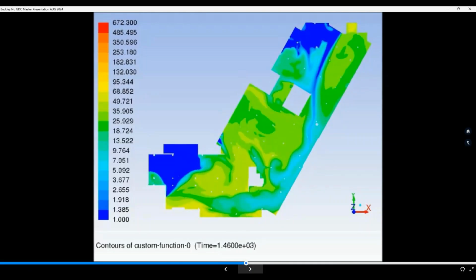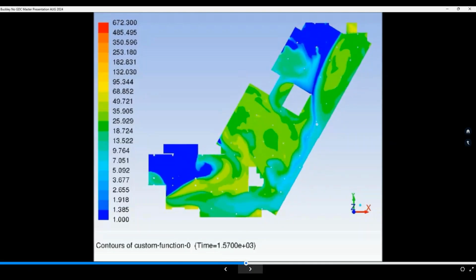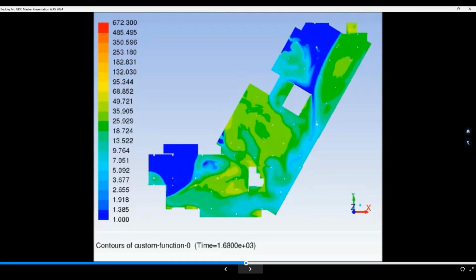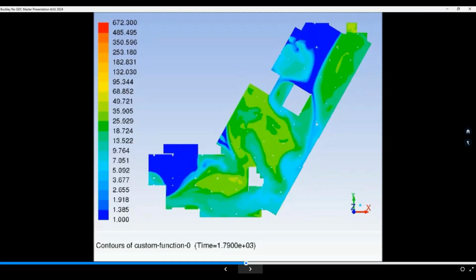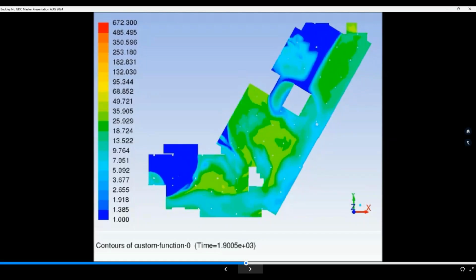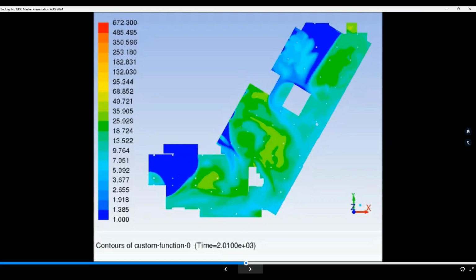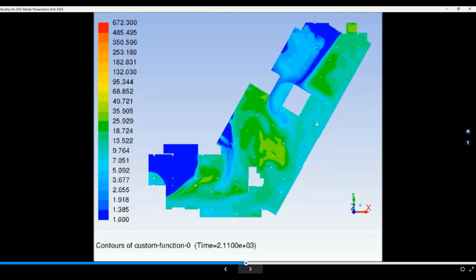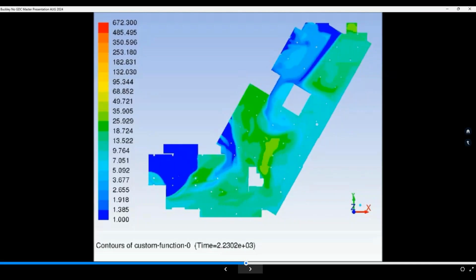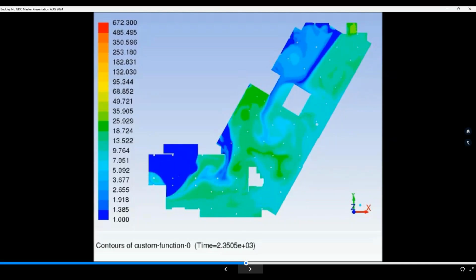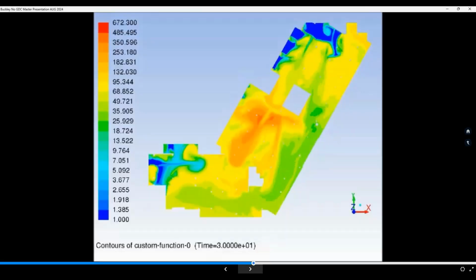Now, at this point in time, the engineer couldn't help this because he was very limited in the space above him because of the green space required. This was the only place he could put exhaust air, and at the top was the only place he could put the inlet air. So considering all this short cycling, we're moving the correct volume of air. By code and standard, this meets the requirement of moving 0.75 CFM continuously, but the space is not getting the maximum benefit of the ventilation rate introduced.